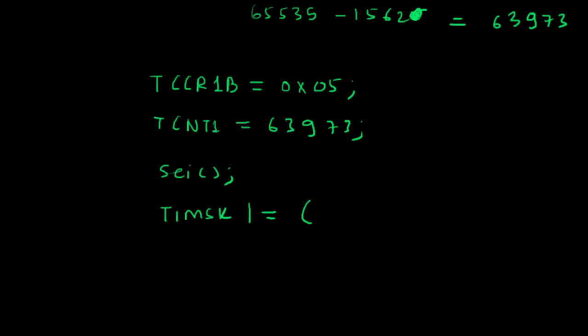So with bit set operators, we can directly write without looking at the register. So we'll set the register TIMSK, and the flag or the bit that we need to set is TOIE1, timer overflow interrupt 1. With this we enable the exact interrupt. Now we'll go ahead and do this and also write an interrupt service routine. I'll just show you that on the studio itself, and we'll blink an LED as well as display some numbers